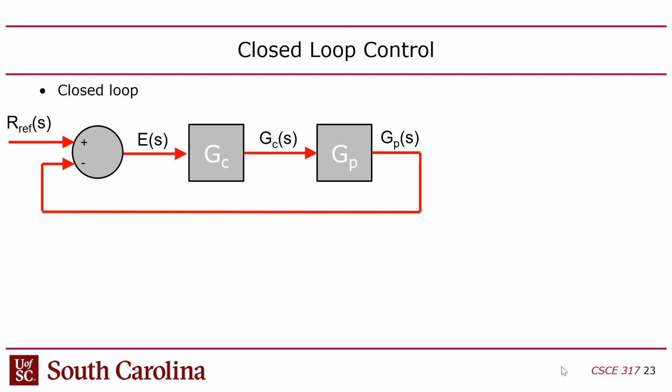This is where we want the coin to be. So this is like saying, okay, you want the robot to move the coin, I don't know, 10 centimeters or something, right? So that's the set point. We take where the coin is, the position Y, and subtract that from the set point, which creates an error, and the error is what we feed in as the input to the controller. Does that make sense? You might have seen something similar to this in 274 when you took robotics.